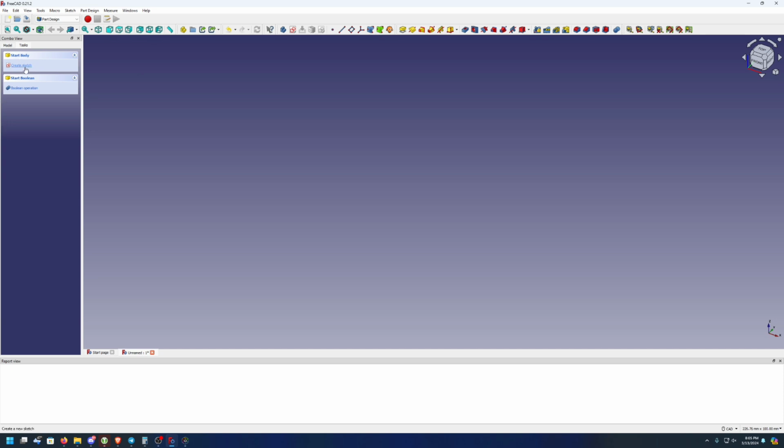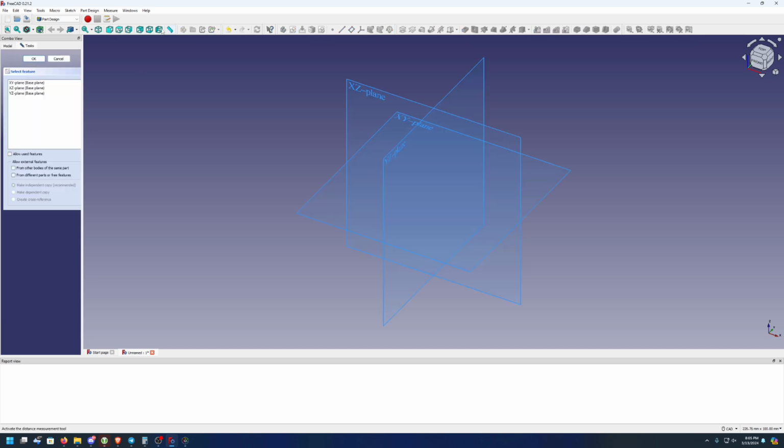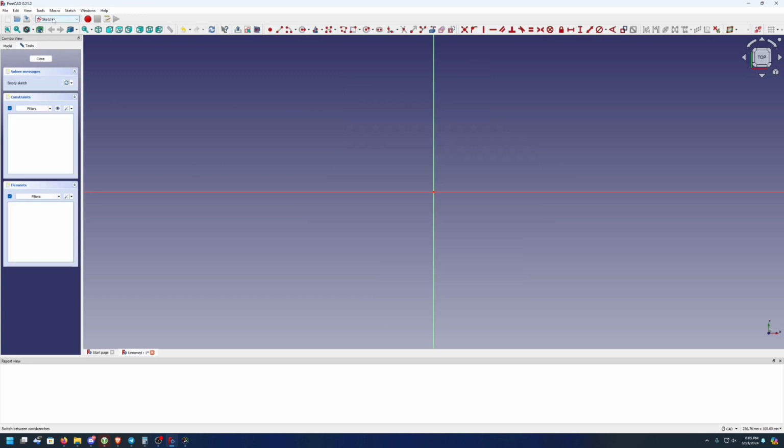With that, now you can create a sketch and you select a plane. I almost always do X, Y, unless there's a reason, because if I'm building something and I export it as an STL, generally, if I treat this as the bottom, it will come into my slicer software in the correct orientation. You can see Sketcher is now the mode we're in. It automatically did that, and we're able to start drawing.